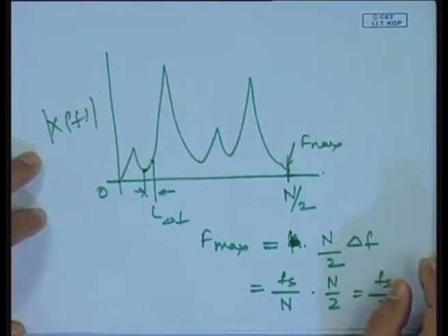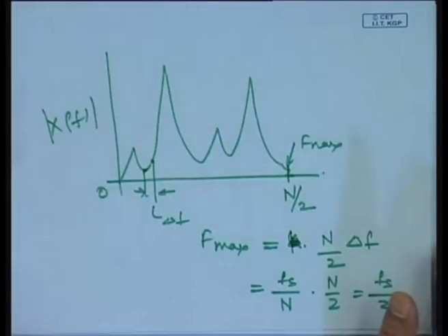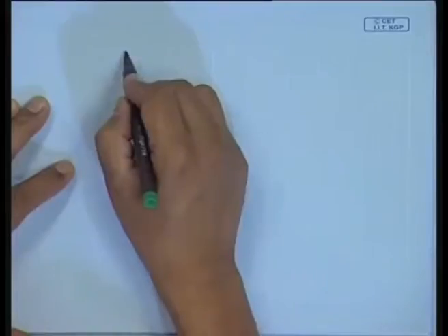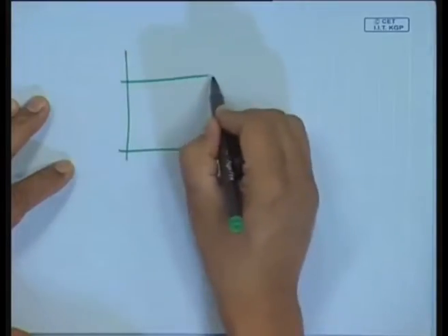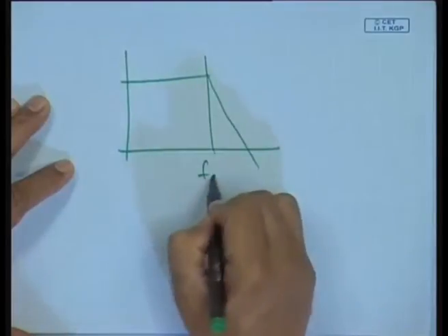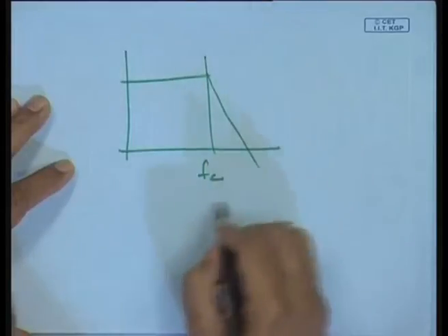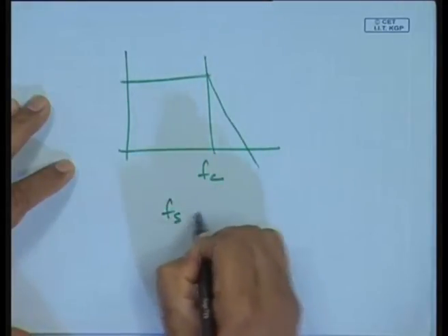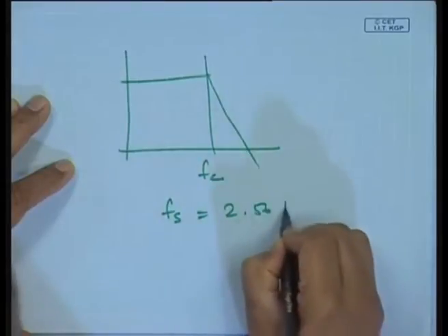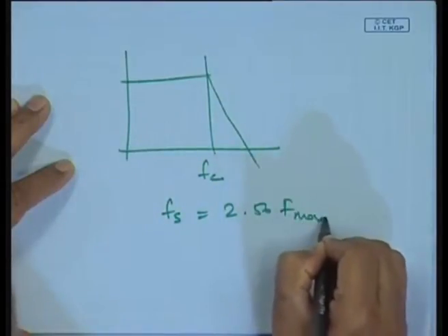So, when I am talking about analyzing an audio signal out of a CD player coming out at 20 kilohertz, I should sample at 40 kilohertz and above. And usually, because of certain filters, they have a roll off, when I say a low pass frequency at FC, because of this roll off, some data comes through. So, usually we sample at a value of 2.56 times F max.